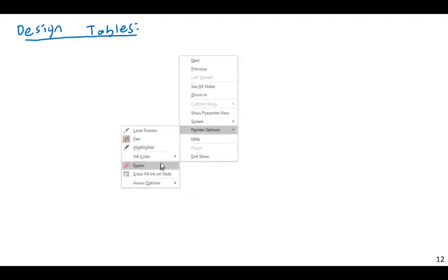Now, these are found in chapter 3, a series of tables that aid us in calculating beam capacity. So basically, you've already seen so far that calculating beam capacity for steel beams can be quite involved. We have to worry about lateral torsional buckling, we have to worry about local buckling, all of these things. And so if we can have some pre-made calculations effectively, that can really help us move through things a bit quicker.